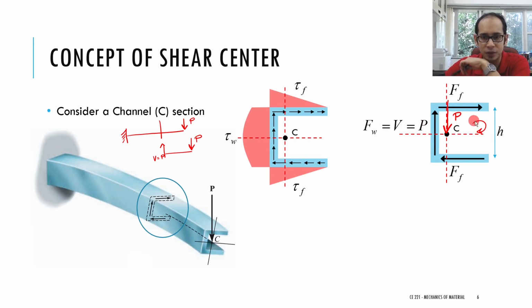So as a result of this twisting, we saw that you're having the twisting in the beam over here. Now you see what is there in our hand. What is there in our hand in terms of this beam? We cannot do anything with the beam. The beam is as it is. In our hand is where we can apply this force P so that it cancels out this twisting moment that you're having, and essentially does not let the beam, along with bending, twist.